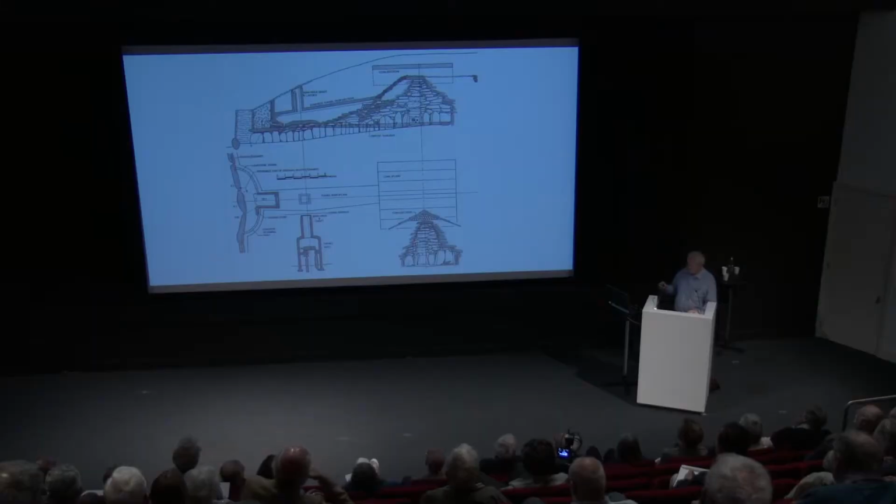That applies enormous pressures that would easily break the ordinary lintels with which we cover the passage. Not only that, but because there's a gap in the tholos, which relies on its continuity for its stability, the tholos that form the sides of that gap, they're free to move in now. And when that happens, it'll destabilize the whole structure. So a huge amount of Scottish Drystone engineering relates really to that junction there.